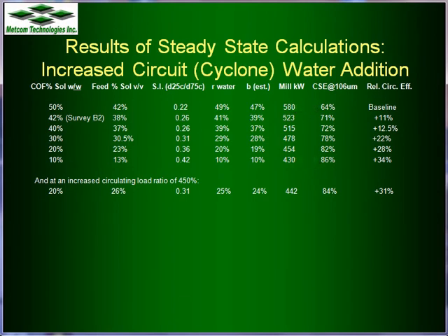This showed us that by installing a thickener after the grinding circuit, for example, to deal with all the extra water ahead of CIL processing, that the efficiency of the grinding circuit could be increased by approximately 30%. The thickener was installed, and the grinding circuit significantly outperformed all previous production.